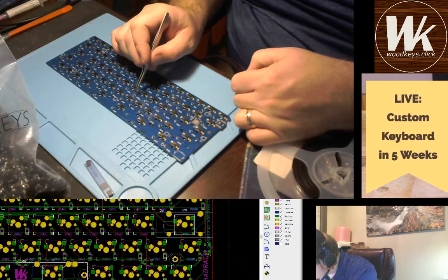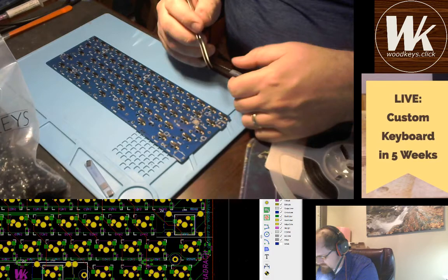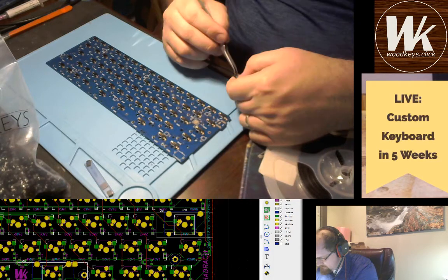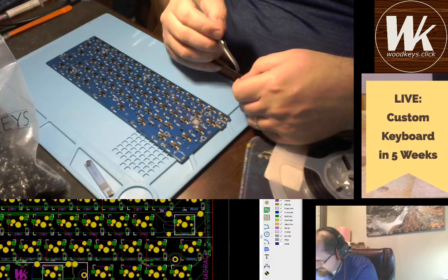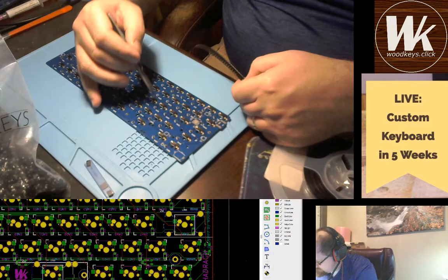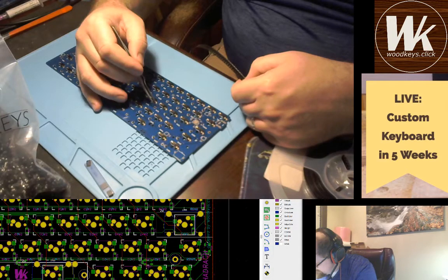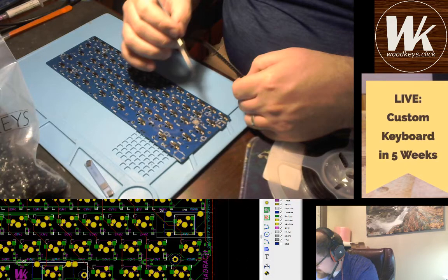So one thing when you're laying out the PCB that I may not have mentioned before is that it is a very good idea, because of what you're seeing right here, to ensure that all the diodes are facing the same direction. Might not seem obvious. Might seem like a good idea to switch them up to make the layout easier to do or whatever, but if you don't have them all the same direction, you're in a world of hurt when it comes to populating the board.